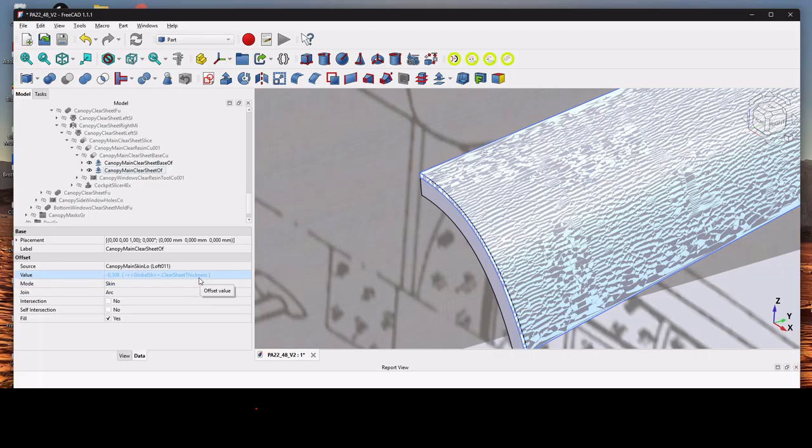So when you thermoform, usually you are taking sheets of plastic that are 0.6, 0.5 mm thick. But when you stretch them using thermoforming, it goes down to something like 0.3 mm thick. So I need the mold to be 0.3 mm thick from what I'm shooting for, in order to leave the space for the material to be there.